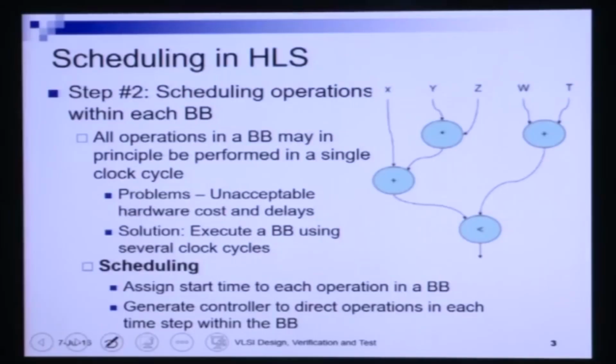Until we have ascribed explicit timing information to each operation within a basic block, we cannot ascribe the complete timing information of the module. Therefore, to obtain the complete master controller, we need to ascribe timing to operations within a basic block, and timing to operations within a basic block is done through scheduling.